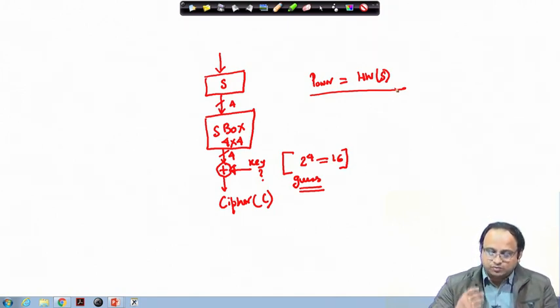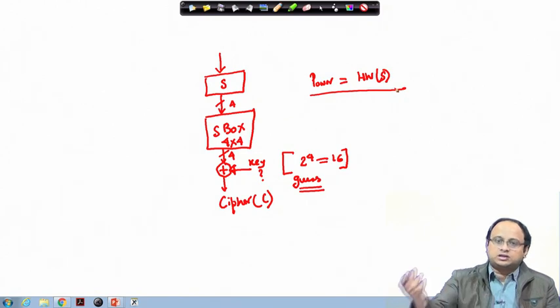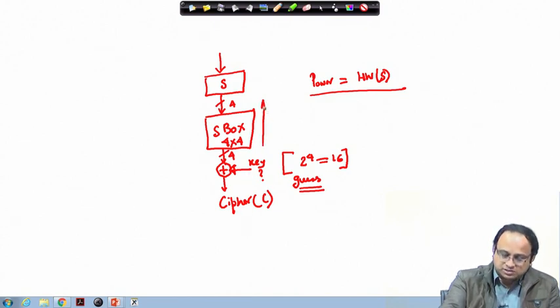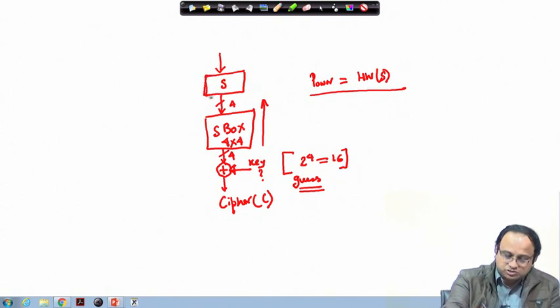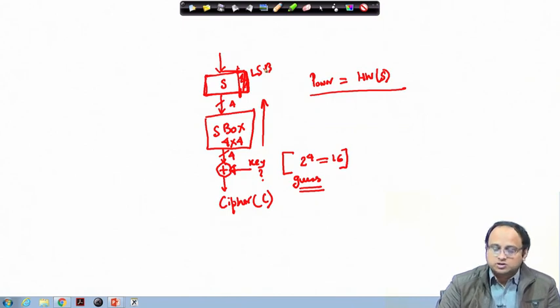Now what we will see is that with this power information, you can distinguish the correct guess from the other wrong ones. How can you do that? You will guess this, you will XOR with the cipher, you will take the inverse S box. Okay. So if you take the inverse S box, you will come to this state S. Okay. So imagine that I just take the LSB of S. I basically take the inverse and I just find out what is this LSB. Okay. And now I essentially do the splitting as I told.